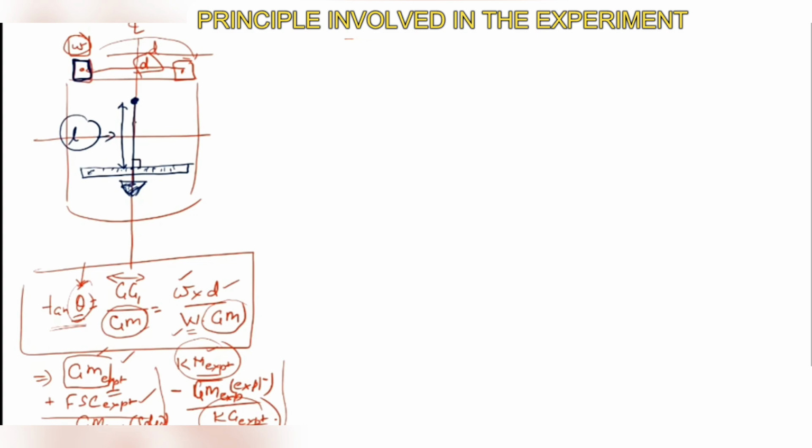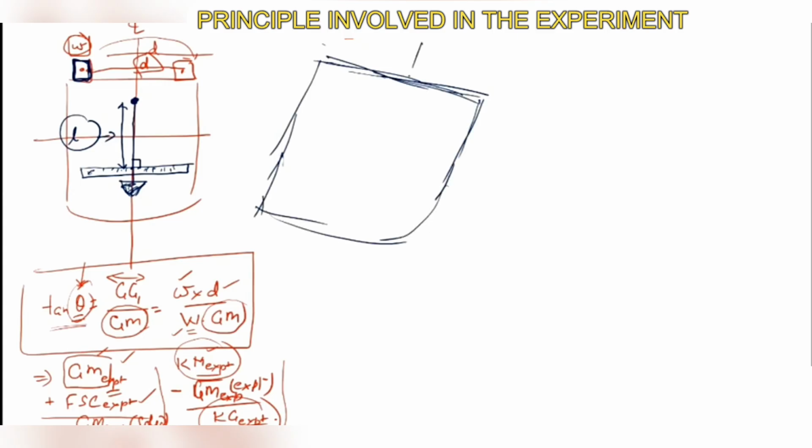This is the pendulum we have suspended. We have a graduated batten. The vessel is upright with the weight in the blue position, right? The vessel develops a list. I'm exaggerating the list. That will depend on how much weight is shifted and what is the displacement and all those things. I'm just exaggerating the inclination. So now the weight is no more here. The weight is here. It has been shifted through a distance d.